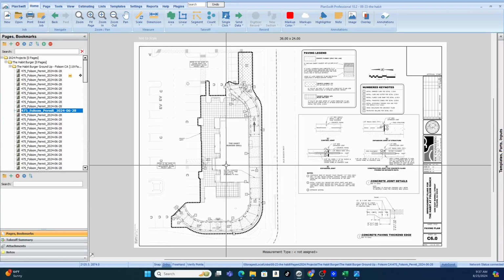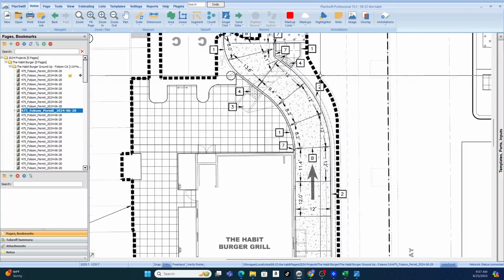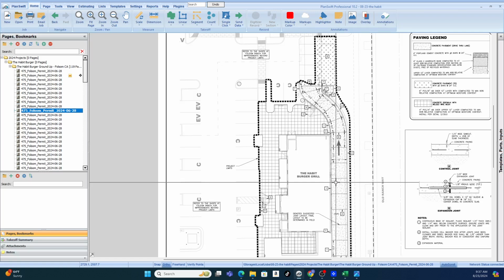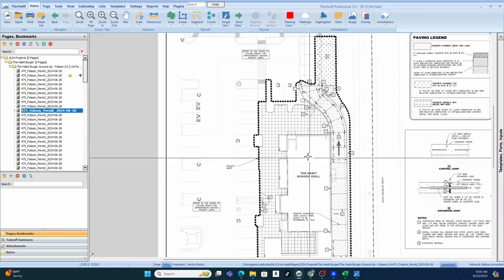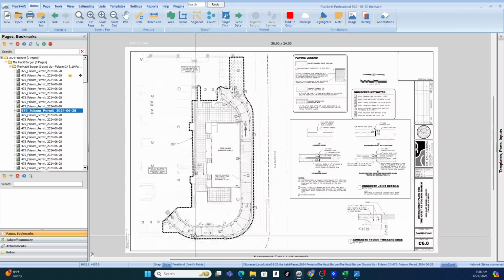All right. Utility plan. Paving. That's easy. Right. You just need to have a good tool. And let's see. When we're doing curbs, we have a straight portion, and then we have a curved portion. When you're doing the takeoff, measure curved separate from straight because it's more labor. And so this is very easy. What do they give you? A and B. We've got some control joints, probably.